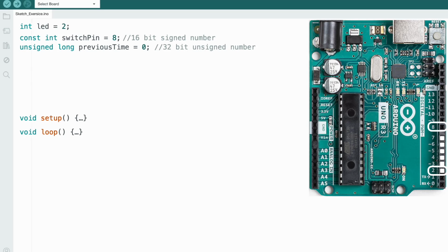In this case, when we start talking about timing, and you're incrementing a timer 1,000 times a second or 10,000 times a second, depending on the processing speed of your CPU, if you have a small value for trying to calculate up time, you're going to run out of numbers very, very quickly.